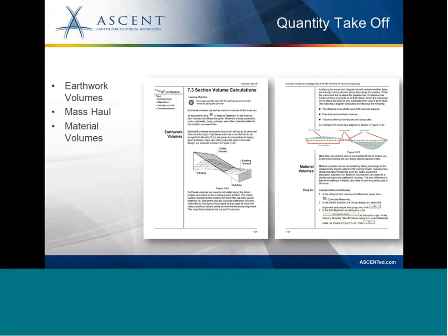All right. Once you have the corridor created, then you go in and you create the finished ground surfaces so that you can do your volume calculations for your earthworks. And you'll do volume calculations for your cut and fill, and then go through and do a mass haul diagram to help you understand the cost that's going to be associated with building this road.